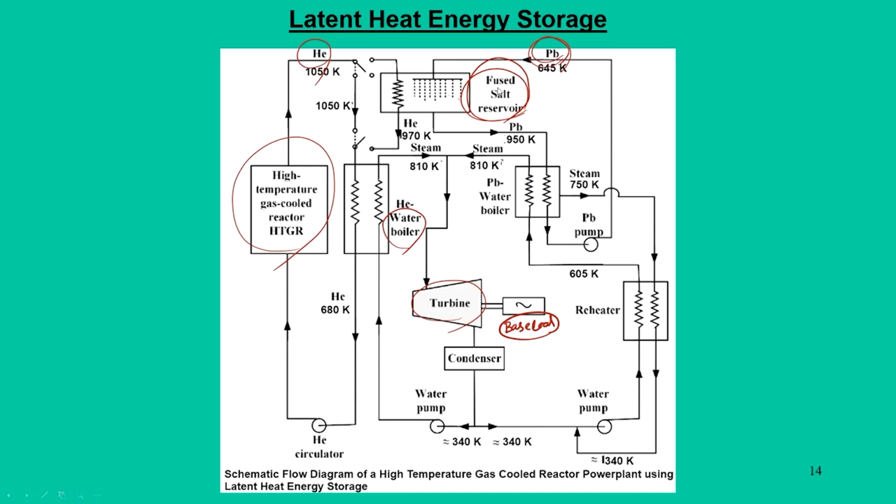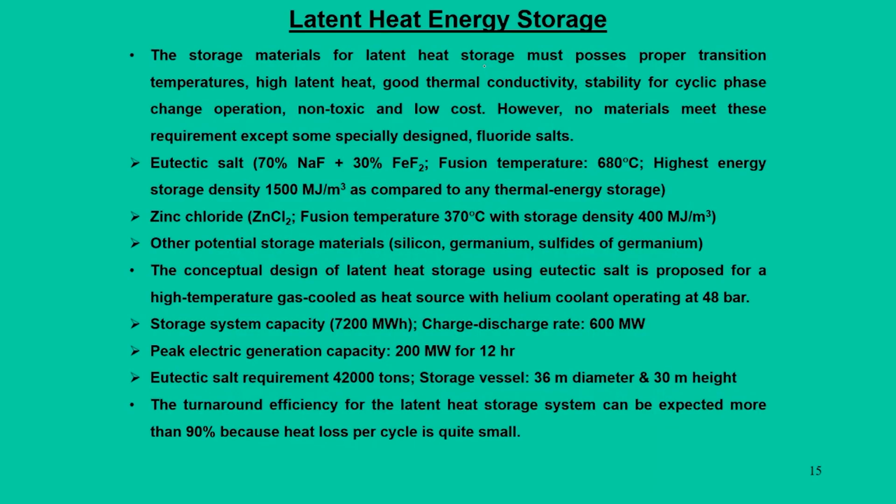So, the efficiency of these latent storage systems mainly depends on what type of fusion salt we use. For that reason, we have mentioned some of the requirements of the storage materials. Storage materials for latent heat storage must possess proper transition temperatures, high latent heat, good thermal conductivity, and stability for cyclic phase change operation, and the material should also be non-toxic and low cost.